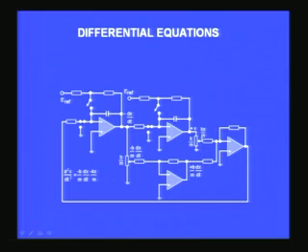Then you provide the corresponding k by m x proportionality here, and here dx by dt is multiplied by a proportionality constant minus b by m using this potentiometer. That output is just inverted, because this is minus here, this will become plus, and these two terms are now added, and that is what d square x by dt square is. So that is given at the input here. So you find this becomes a consistent circuit with the input and the output conforming to each other,